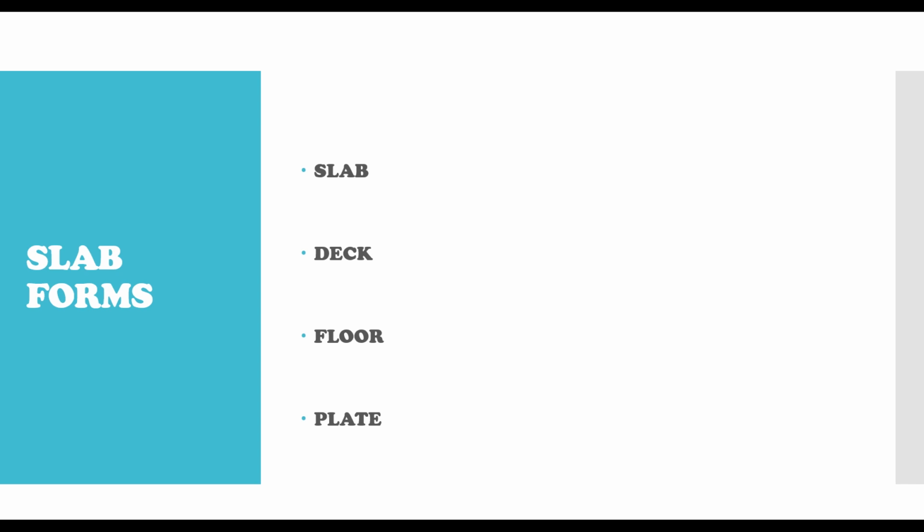Then we also have what we call plates. Plate is commonly used in steel structures, and then you specify the thickness. So generally we are referring to the same structural element, which is a slab. And one of the characteristics of a slab that you have to know is that a slab is an area structural element. So when you are trying to categorize or estimate the loadings on a slab, what should come to your mind is that the loading must be in an area form.